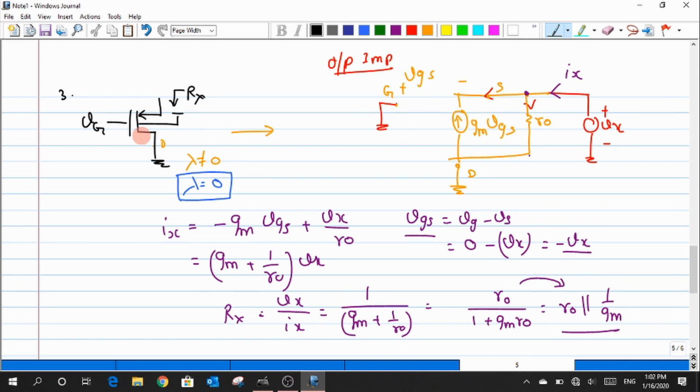It goes to an AC ground, am I right? Because VDD is a DC source, when I translate to my circuit, the body would go all the way to the ground, AC ground. So now I'm just comparing a potential difference between the body and the source. Is there any potential difference? Yes, because body is at ground, but the source is at the most negative potential, due to which there is a VBS. Now whenever there exists a VBS, how will I draw the current direction of it?